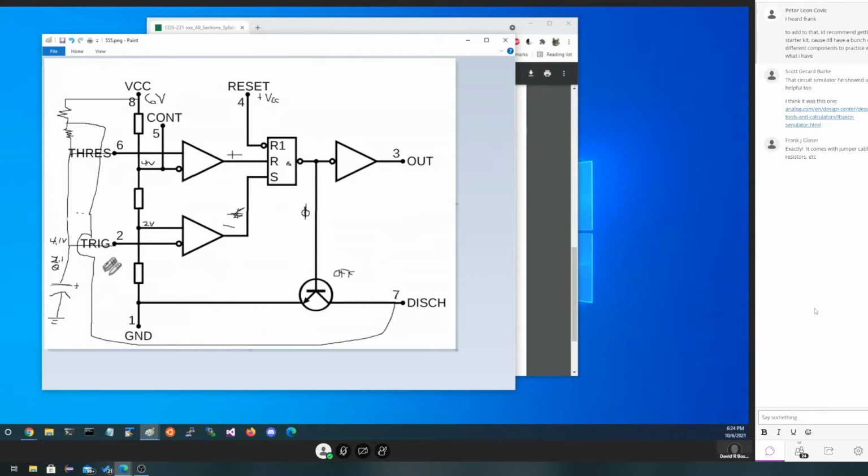Well, where is discharge hooked? Discharge is hooked through this resistor to the top of the capacitor. So even though this reached 4.1 volts, now it's going to immediately start discharging. And it's going to keep discharging until this is dropped down to less than 2 volts. When it does, this guy actually stopped pushing the button as we passed back through 4 volts, but this guy will push the button again to set it and close off the discharge the moment we get down.